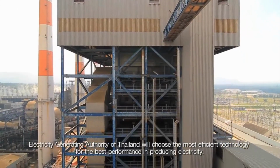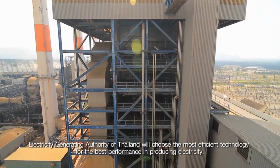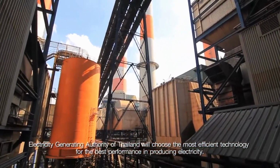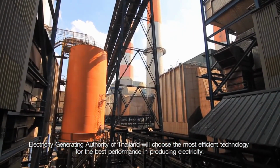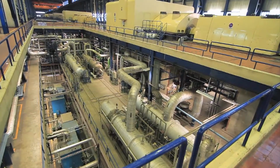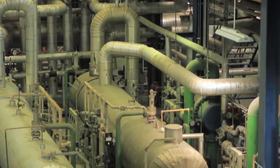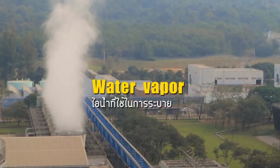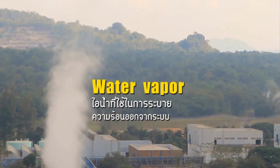Eliminating contaminants during combustion, our clean coal technology power plant has a method to increase efficiency of the furnace to capture pollution during the combustion by injecting limestone and pulverized coal into the furnace. The limestone will act like a sponge to soak up 90% of the released sulfur during the combustion. 90%! That's not all. The combustion temperature during this process is lower than the temperature in the former process. As a result, the lower combustion temperature also reduces nitrogen pollutants in the coal.